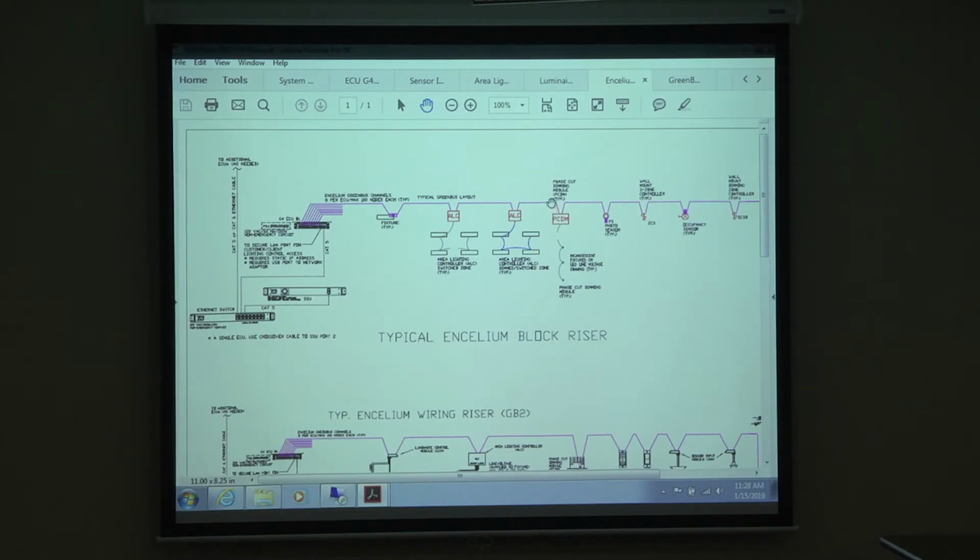And in the software, it brings you down to close proximity as to where the issue is happening, because in the software all these devices are color coded per channel. So one channel is gold, the other channel is green, blue, red, purple, right? So based on what happened, you can see some devices will have an X on them. That means they are disconnected going down the side. Anything with no X is downstream to the ECU, and that's fine. And the software makes a lot more sense once you see what's happening in it, right?